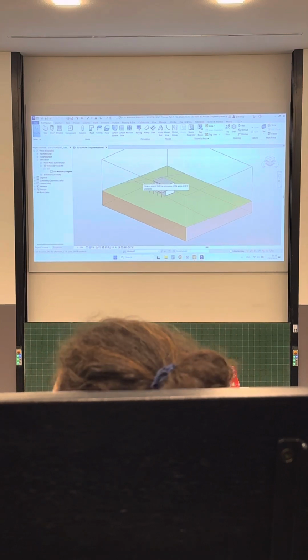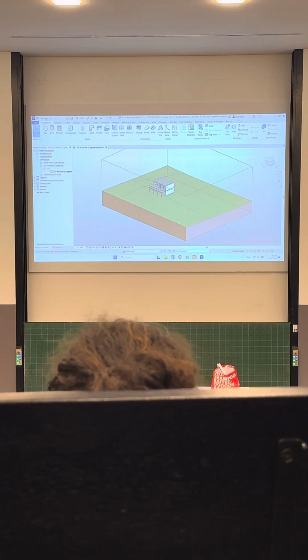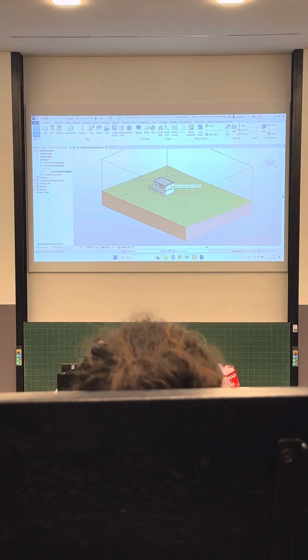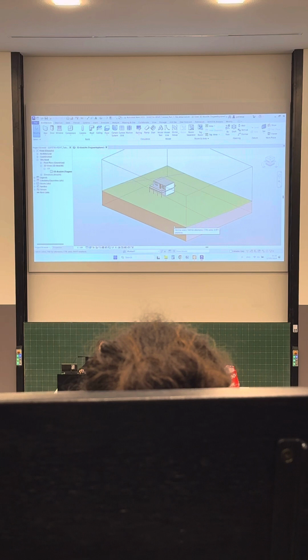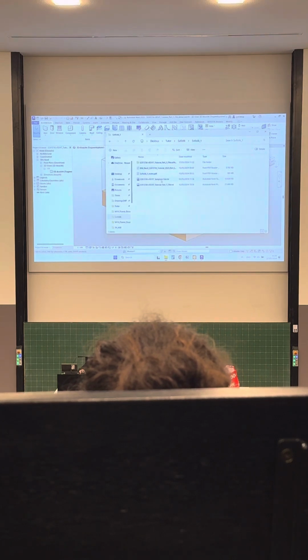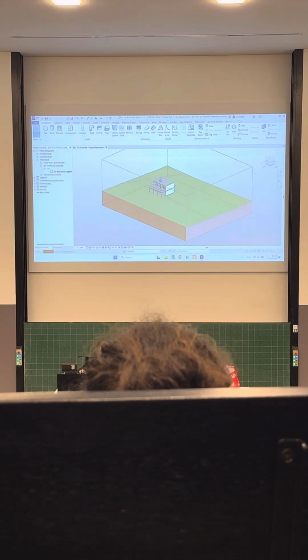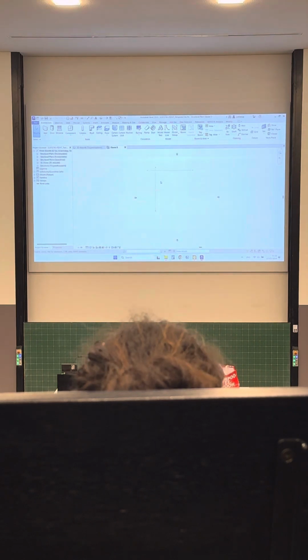And we'll go through the steps of, for example, you get this model of architecture and you need to do now structural analysis. I will walk through all the steps of structural analysis in Revit and Sophistic environment. Okay, after opening the RVT file here, hope you don't have this error again. You also open the RTE file. Now you can just double click and it will open in another tab here.